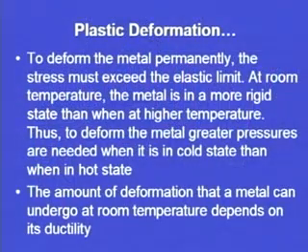At room temperature, the metal is in a more rigid state than when at a higher temperature. So, it is easier to deform a metal in a hot state than in a cold state. Thus, to deform the metal, greater pressures are needed when it is in a cold state as compared to when the metal is in a hot state.